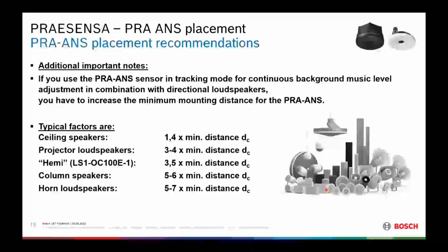And then, of course, the only way to test if my noise sensor works the way I would like it to is to use a noise source which you bring into the zone. This could be a powered speaker with a noise generator, and you just play some noise into the zone, and also here stay away with this artificial point source for noise.